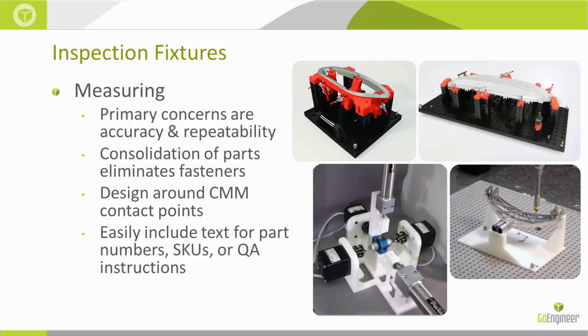For storage, you might take that apart and put it back together. In a shop environment, again, you take something, put it back together. Who knows what sort of metal chips got in between there? Who knows if you pinned it or not so that the screw holes are aligned perfectly? Things happen, right? So by printing that in a single part, you eliminate all of those concerns. That's kind of where I'm getting at there.